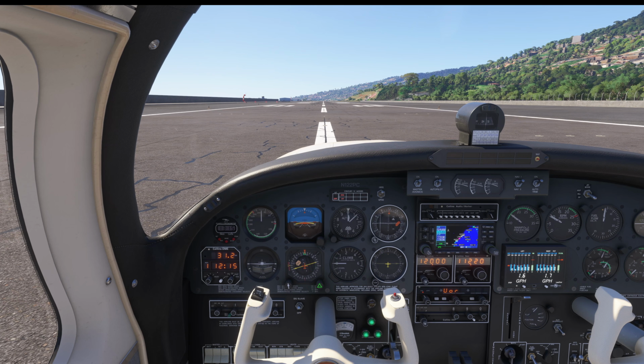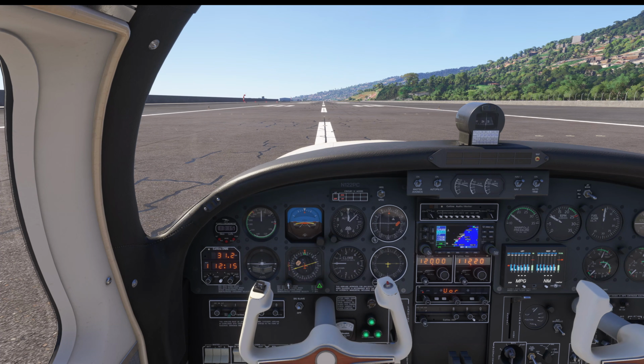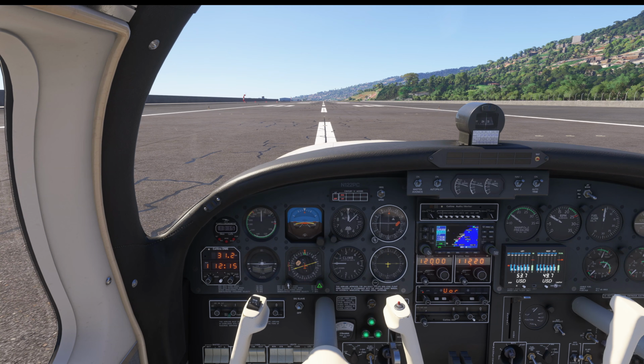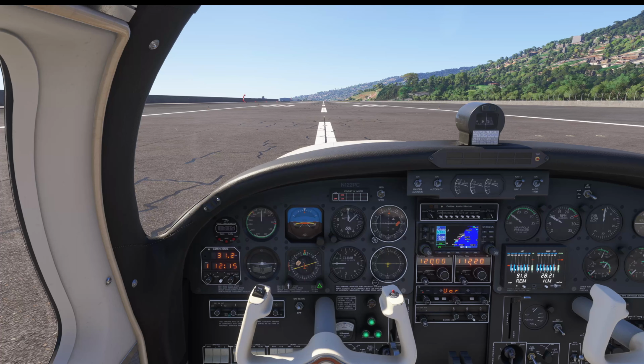I will show what the pitch sync button does later when I get the aircraft up in the air. But before that, I also want to talk a bit about the pitch trim. In real life, most autopilots control the aircraft like a human would, with servo motors connected to ailerons and elevator. Then, elevator trim is used to reduce the load on the elevator servo. And with our custom autopilot code, we can have both elevator and trim under autopilot control interacting with each other.